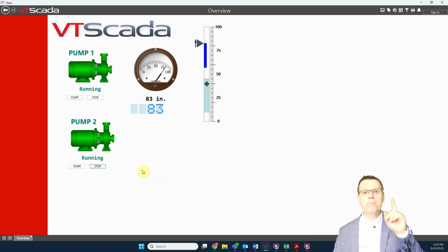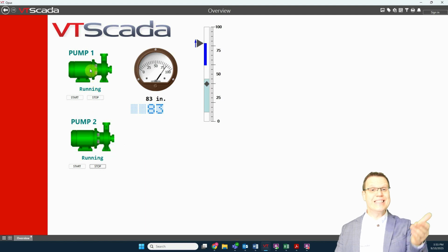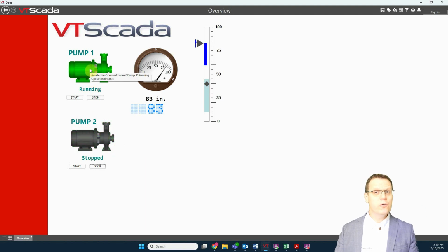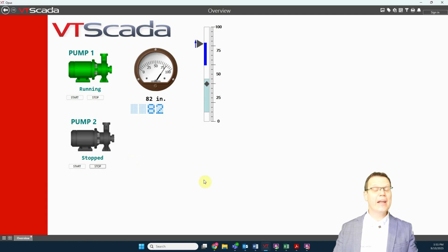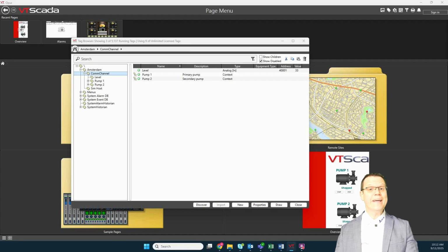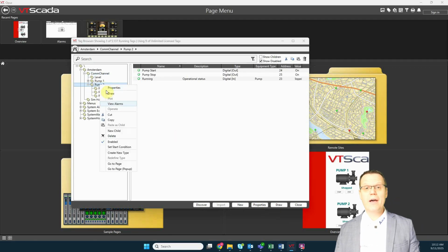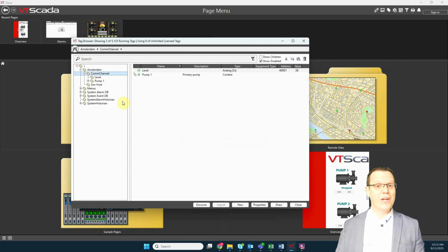This is an efficient method for creating multiple instances of the same equipment. But what if we need dozens or even hundreds of similar objects? That's where an even more powerful approach comes in. Let's move into a more advanced mode and create pump controls using dedicated widgets and parameterized pages. For now, we delete pump2 because we are going to recreate it using a custom type.